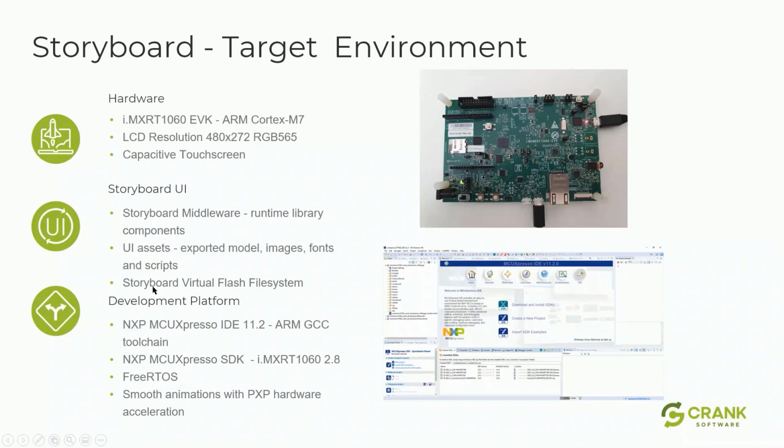And this will be in the Storyboard virtual file system format. In terms of development platform, we're going to be using MCUXpresso IDE 11.2. Of course, that's the ARM GCC toolchain. And we're also using the 2.8, I think it's 0.2 version of the MCUXpresso SDK, which comes with FreeRTOS, and of course we'll be making use of the PXP hardware, and I'll show you that in action.